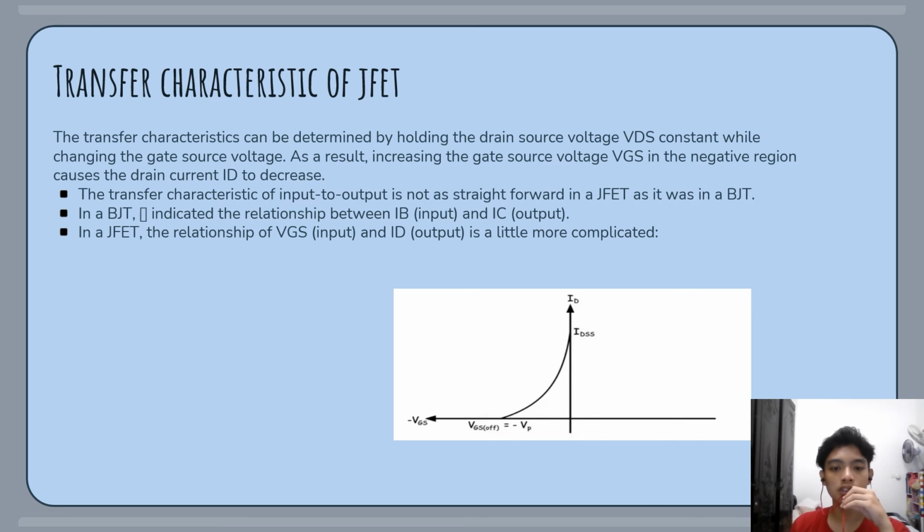By keeping the drain-to-source voltage at pinch-off voltage, the transfer characteristic is drawn between gate voltage and drain current. The maximum drain current flowing through the transistor when the gate is at zero potential is known as shorted-gate drain current, IDSS. As the gate negative potential increases, the corresponding drain current decreases. The drain current becomes zero after a certain negative gate voltage. The gate-to-source cut-off voltage VGS(off) is the negative gate terminal voltage at which drain current becomes zero for the applied drain-to-source voltage, which is the same as the pinch-off voltage.